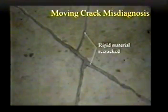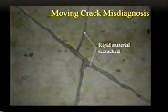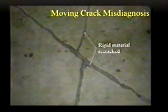Okay, here's that moving crack, with a misdiagnosis. This is an epoxy material, a rigid material, put into a moving crack. I'm not here to say epoxy is a bad material. It's an excellent material, okay, in the right place. But because this crack is moving, maybe we should have thought of something different. Maybe it should have been a flexible material, something that could absorb that movement and move along with that crack.